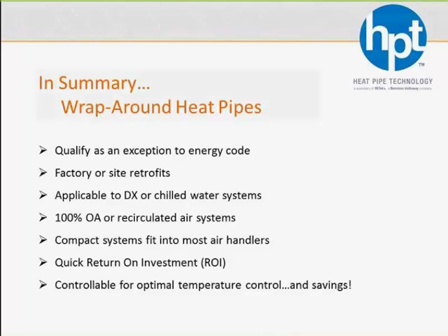They're installed in the factory, whether it's ours or the air handler guys', or we'll do it on the job site. Chilled water, DX, doesn't matter. We do it all. The more outside air, generally the better, but even a recirculated air system, if there's humidity to be controlled, the way the heat pipe looks at it, that's always a 20-something degree delta T, so there's always going to be some free reheat and some free cooling as long as you want it to be done. Still going to save you some money.